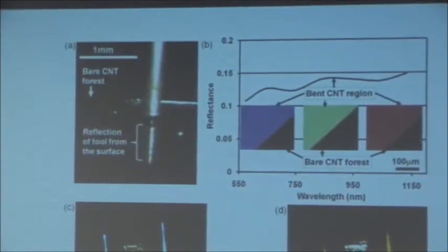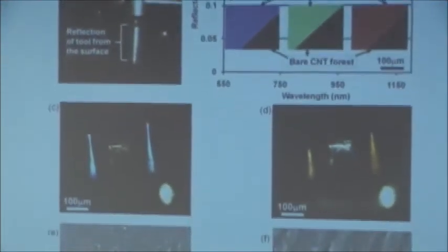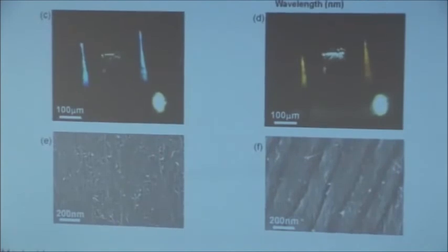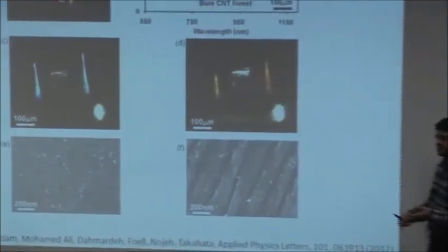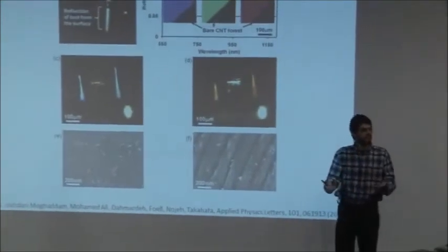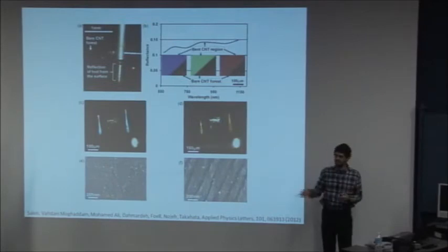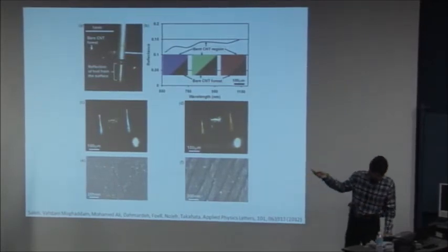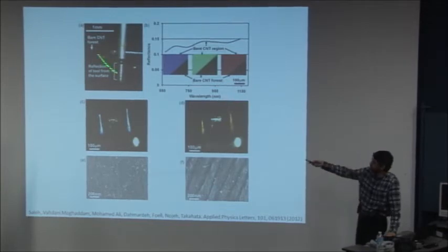So, we took a closer look at this and did a lot of experiments, and it turns out that by simple mechanical polishing, you can turn this, what people claim to be the darkest man-made material ever, into a mirror. Now, this is not the most reflective. The reflectivity of these first samples has been on the order of 15%. But that's something that you can see an image in.